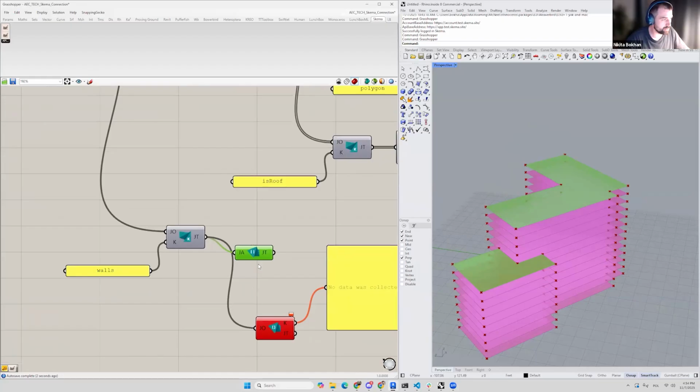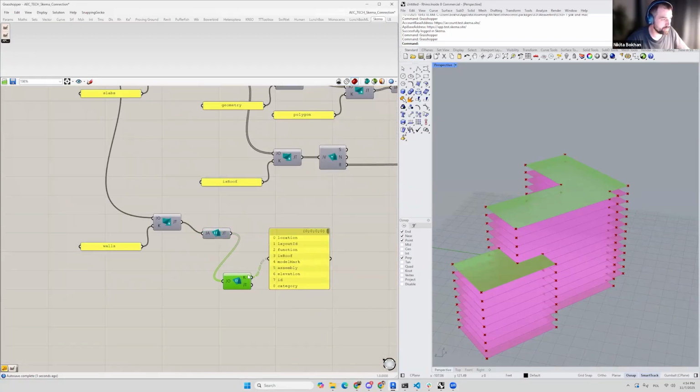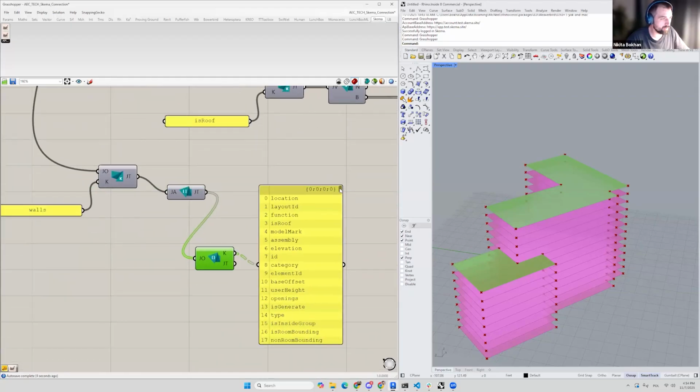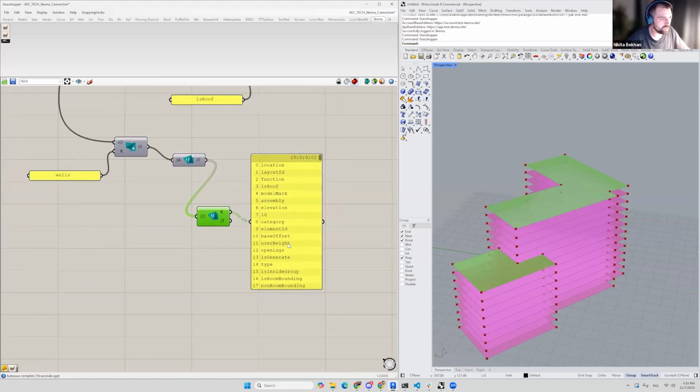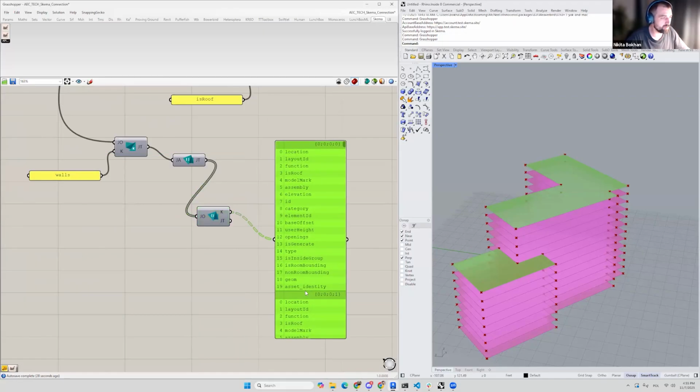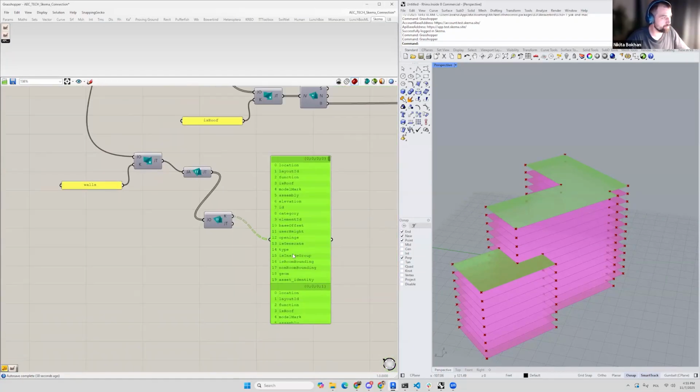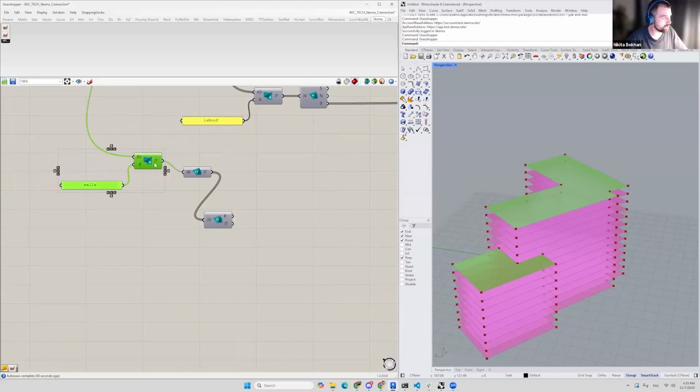As you can see here, this is just one array, and each wall is an object. We have a lot of options for a wall: some offsets, on which elevation it's located, etc. I wouldn't dive into all these details. What we need here in order to reconstruct the wall, because walls are represented a bit differently, is that they are 2D elements right now in Schema, and we need to access a geom property, as you can see here, this one.